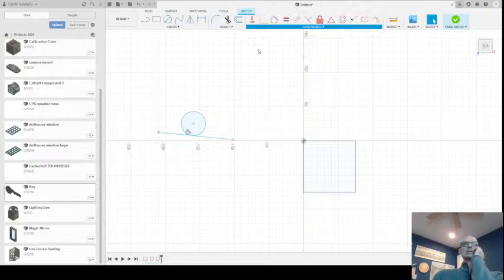To equal, we covered in the square to make those sides equal, and then I forced one into a dimension, which forced the other sides into their dimensions. And by virtue of the horizontal and vertical constraints, force those sides to be all equal.